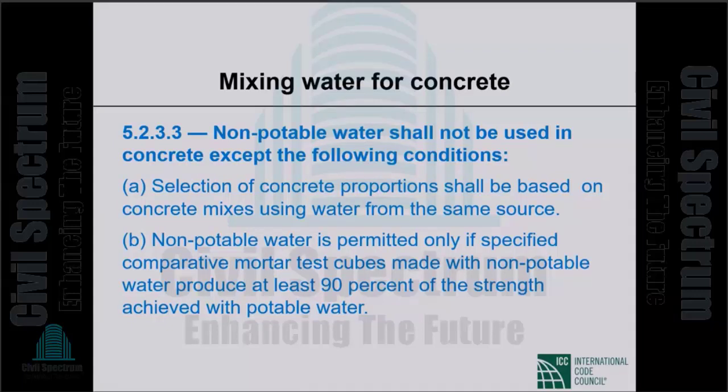Non-potable means non-drinkable. Water that you cannot drink must not be used in concrete making. This is the simple rule. Water that you cannot drink shall not be used in concrete making. As simple as that.